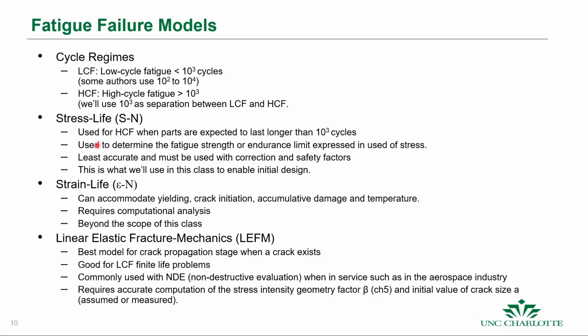It's good for low cycle fatigue, finite life problems, and it's commonly used in tandem with non-destructive evaluation when in service, such as in the aerospace industry. In that case, they use sensors to instrument the structure and actually measure the strain and stresses in that component, and then use that to predict the life.